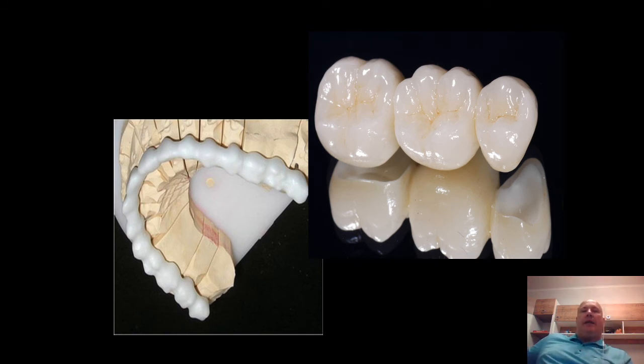Vita Zcubes is pre-compressed and baked yttrium-stabilized zirconia. It's very important that milling occurs in the soft phase, while the processing time of the frame and the consumption of diamond mills is reduced highly. After milling, the frames are placed in a sintering furnace, and the frame shrinks by about 20%. They have a bending strength of 900 megapascal applied to each block. It's a very high coefficient.